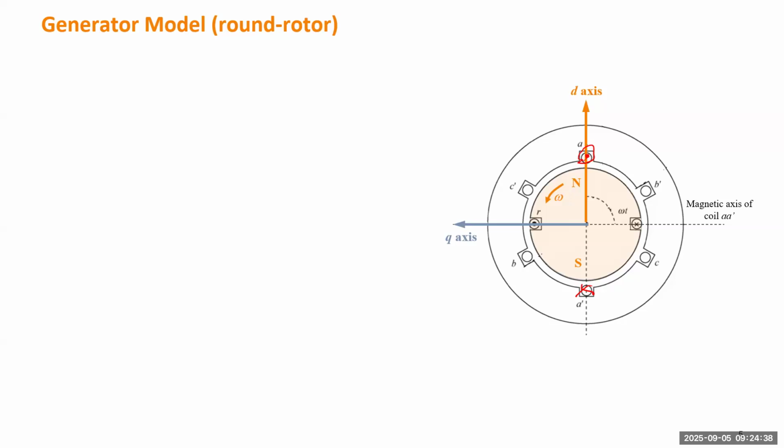Next we want to determine the initial time, which is important because in section 2 we use the cosine function as the basic function to formulate AC current and voltage. We still stay with the cosine function because we need to write down the expression for how the flux linkage changes. Under static state conditions, the field current in the rotor will be constant.